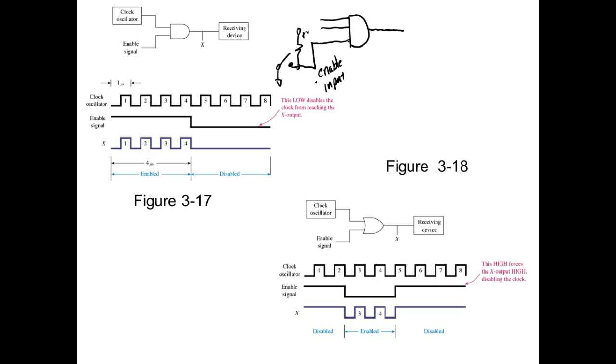So what would happen is, I'm using this as a what? Enable. So what we're saying is if I come over here and put a 0 out there, this output's going to be a 0 no matter what those other two inputs are doing. And we'll call this signal A and B. So if this is a 0, A and B means nothing. We got the gate closed.